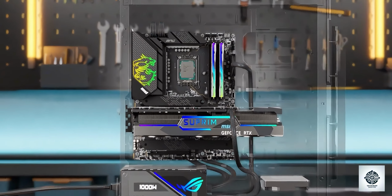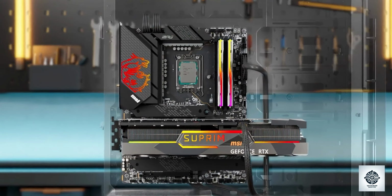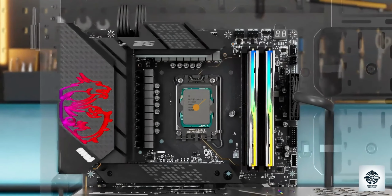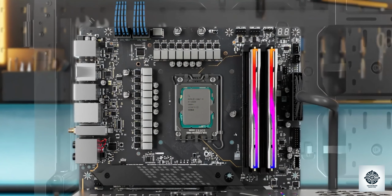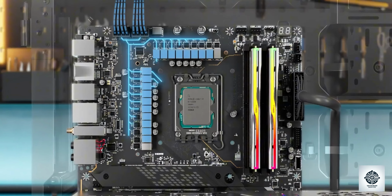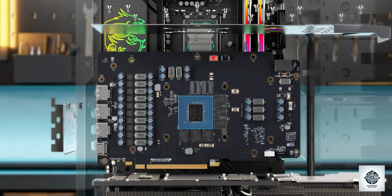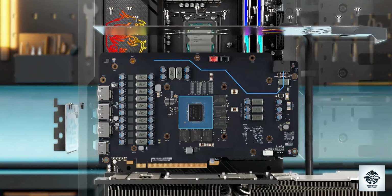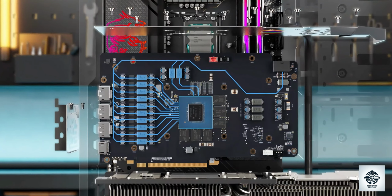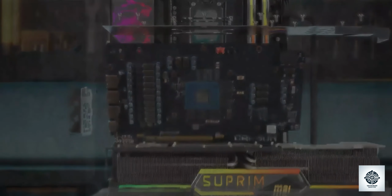In a computer, the CPU and graphics card are the two components that consume the most power. They primarily use the main power supply to operate, but the operating voltage of the CPU is only about 1.3 volts. Therefore, when power is supplied to the motherboard, it must pass through MOSFETs around the CPU to reduce the voltage to the necessary 1.3 volts. Similarly, the operating voltage of the graphics card core is also only about 1.1 volts. When current enters the graphics card through the PC power supply, it also needs to be stepped down before being supplied to the graphics card core.